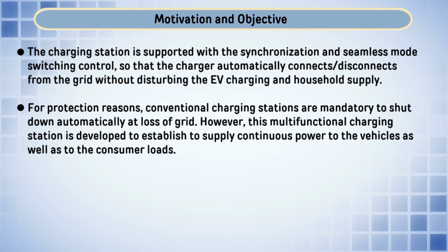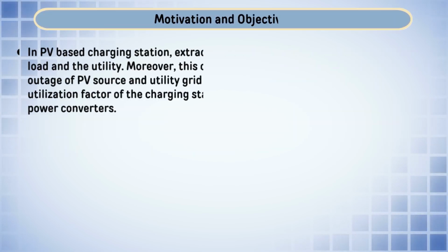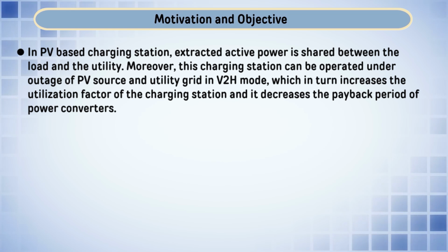The difference between load voltage and grid voltage must be between 0.88 to 1.1 per unit, and the frequency must also be within the limit. In various cases people consider 49.9 as the lower limit and 50.2 as the upper limit. So, under this limit we have to maintain this frequency.